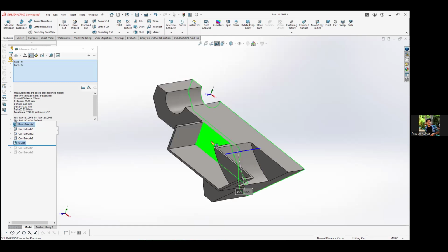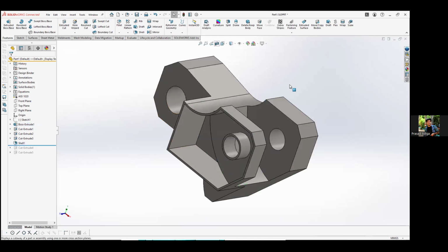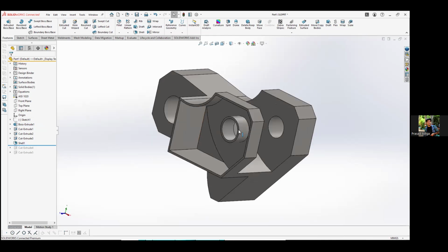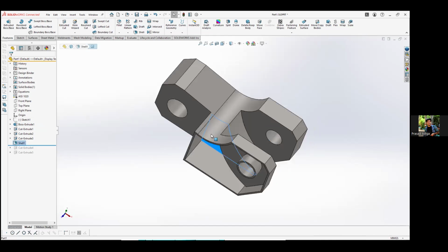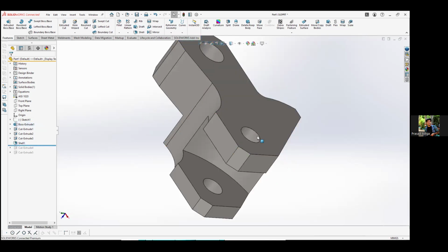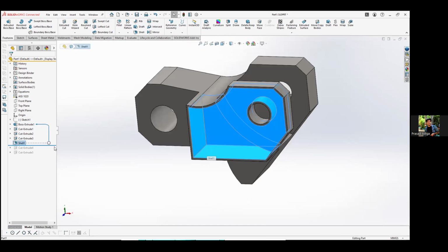Now, yes, it's true, but it creates confusion in users, especially fresh users, right? People start thinking that whatever they have done is now correct. That is the only thing, and they will forget about this particular region and this region, which is not exactly 12 mm from the backside. So that is why if you use shell, you need to create two more cuts anyway. I'm not saying it's wrong, but it is right.